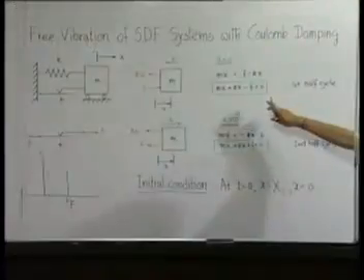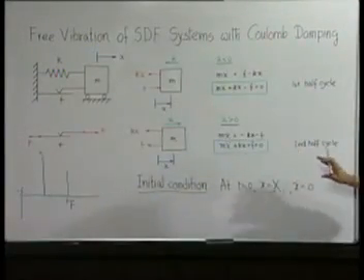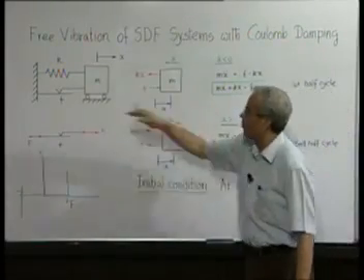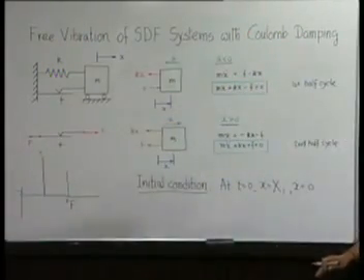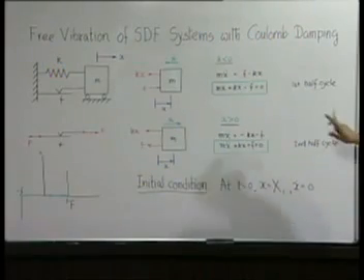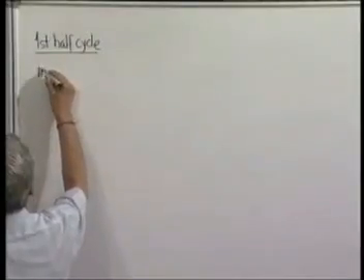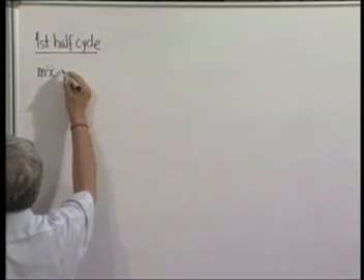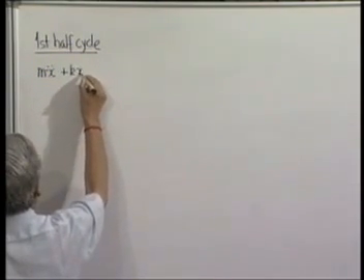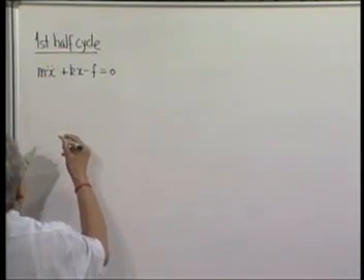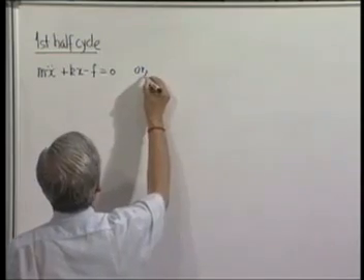What is the equation of motion? This is the equation of motion, because once you bring it to this rightmost position and leave it, the mass will go because of the spring force towards the left. That means x dot is negative, and this is the equation of motion which will be valid. So m x double dot plus k x minus f equal to 0 can be written as...